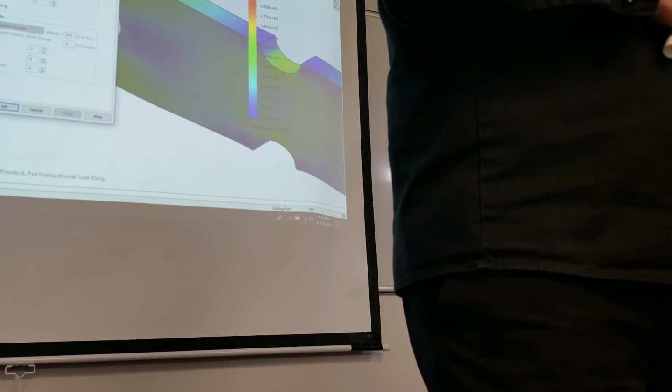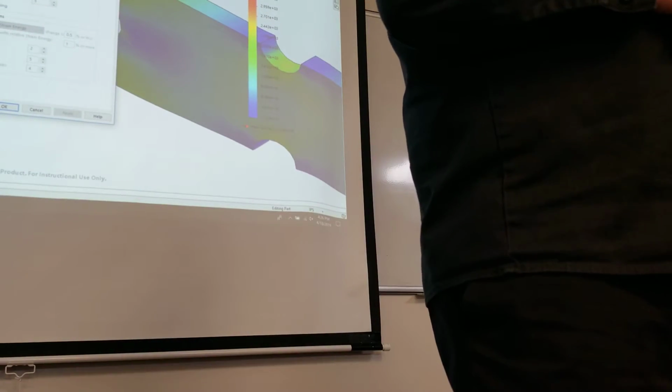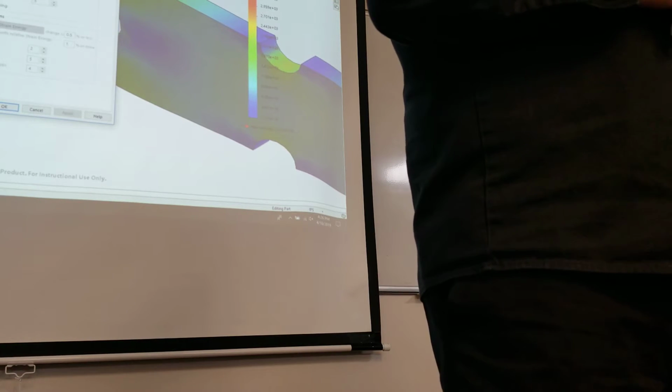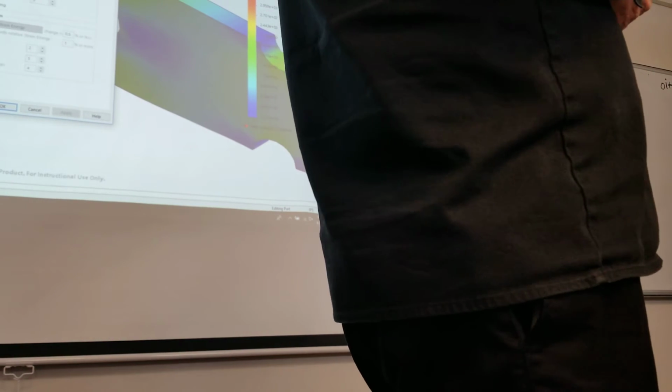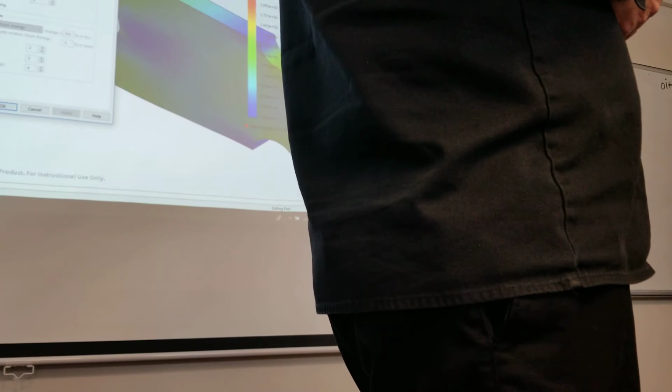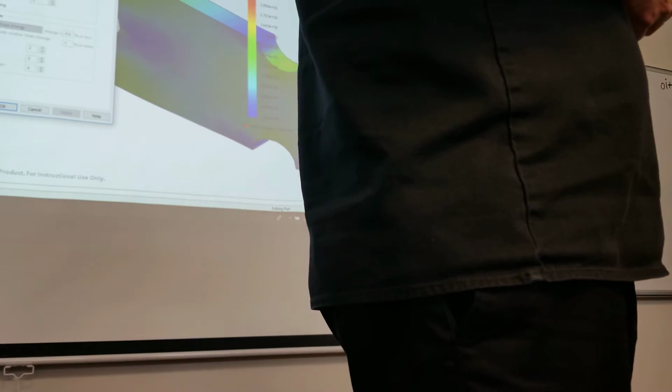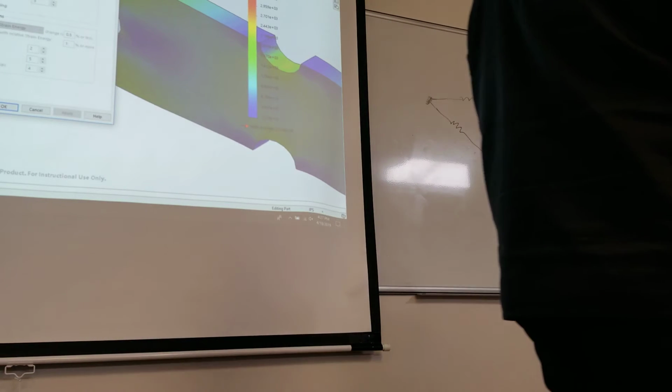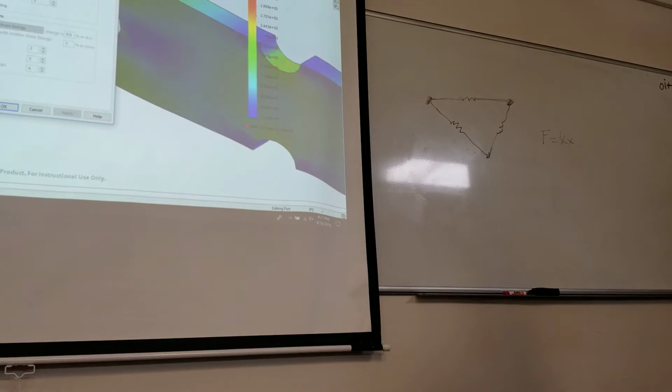No. Can I make a higher order spring that has second order and third order and fourth order and fifth order? So instead of being a nice linear equation, now it's going to turn into some sort of nasty polynomial thing and get worse and worse. And yes, we can. Okay? And that's what a P element does.